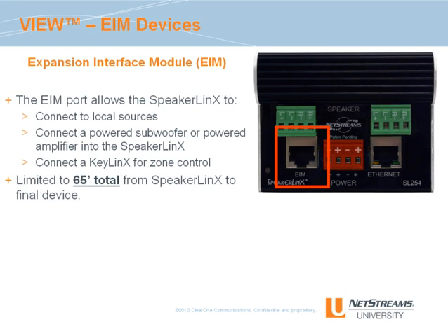A very important design note about the EIM interface is its distance constraint. EIM devices are restricted to a maximum distance constraint of 65 feet from the SpeakerLinks to the final EIM device. So keep this in mind when you're designing systems.